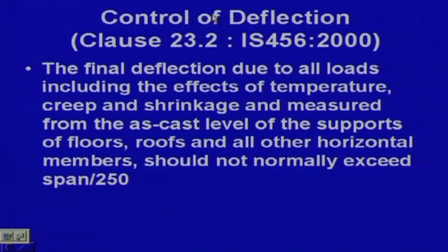Even in the cracked section, if you find cracks, then what will happen? It may be scary, but even if you give a guarantee, unfortunately or fortunately our assumption is based on the cracked section. The design you are doing is actually a cracked section design, that is the assumption. So even if you find cracks, we can say it is still safe, but the users, the residents of that building, obviously it may be scary. It is a little bit of irony, and that is true for all of us also, even if we design.